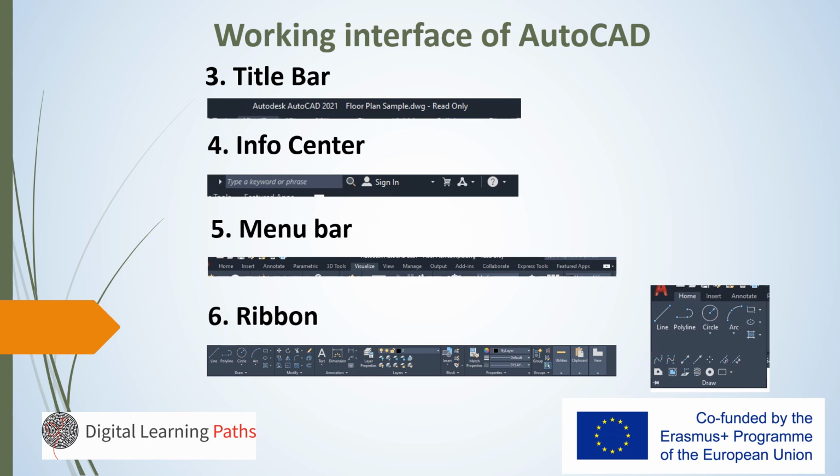Number 4. Info Center. The Info Center contains the Search, Autodesk 360, Autodesk Exchange apps, and Help buttons. You can enter a question in the field to the left of the search button to access information from a number of locations quickly, including the standard AutoCAD help system through the drop-down panel. The Autodesk 360 button allows you to sign in with your Autodesk ID and access a wealth of cloud-based services that integrate with AutoCAD. The Help button is a direct link to the AutoCAD help system, also accessible by pressing the F1 key.